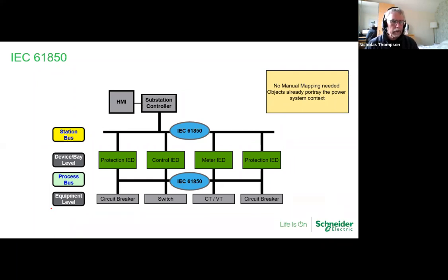So if you are designing data centers, for instance, and you're creating a data center model that is going to be replicated throughout the world using IEC 61850, you do all the hard work with the first model using the right engineering tools, and the engineering tools work across manufacturers. So you have various different codes which IEC 61850 will come into, and you just then design it, take the single line diagram, design your thing using your engineering tools, and then that will write the appropriate programs, and then you basically squirt that into your devices, and hey presto, it should all talk together, and you're using fast Ethernet bus. So if you hear somebody saying, well, we need GOOSE messages for this, it's not the honk honk feathery variety, it is actually IEC 61850.